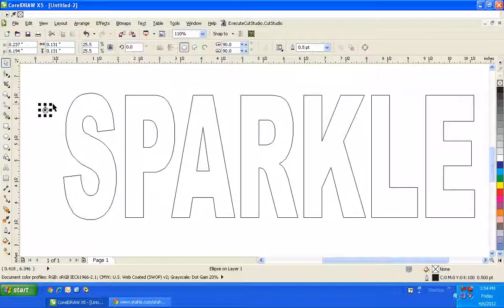So now I have my 3.3mm circle on my screen. I need to make a duplicate of that, so I'm just going to click my mouse and drag it and then right click my mouse. So if you select an object like the circle with your mouse, a regular good old left click, and then drag it somewhere on your screen, you see a duplicate just floating out there in space.